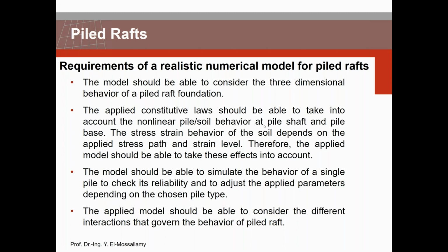Therefore, the applied model should be able to take this effect into account. The model should be able to simulate the behavior of a single pile to check its reliability and to adjust the applied parameters depending on the chosen pile type. So you should be able to carry out a kind of calibration on this pile. The applied model should be able to consider the different interactions that govern the behavior of pile raft.